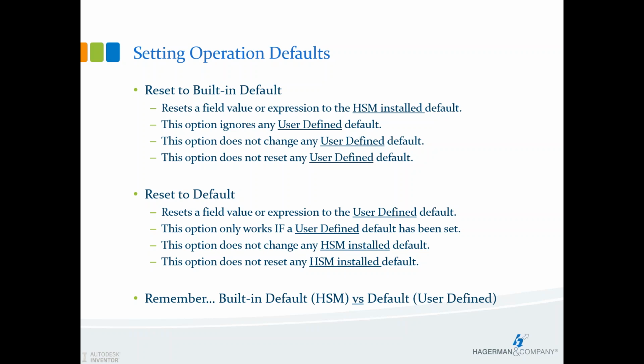The reset to built-in default does not mess with or does not do anything with user-defined defaults. It completely ignores what you have defined as a user-defined. It does not change your user-defined. It does not reset any of your user-defined. So the point is, if you do a user-defined, it's safe. The HSM factory default is not going to reset anything you've customized.